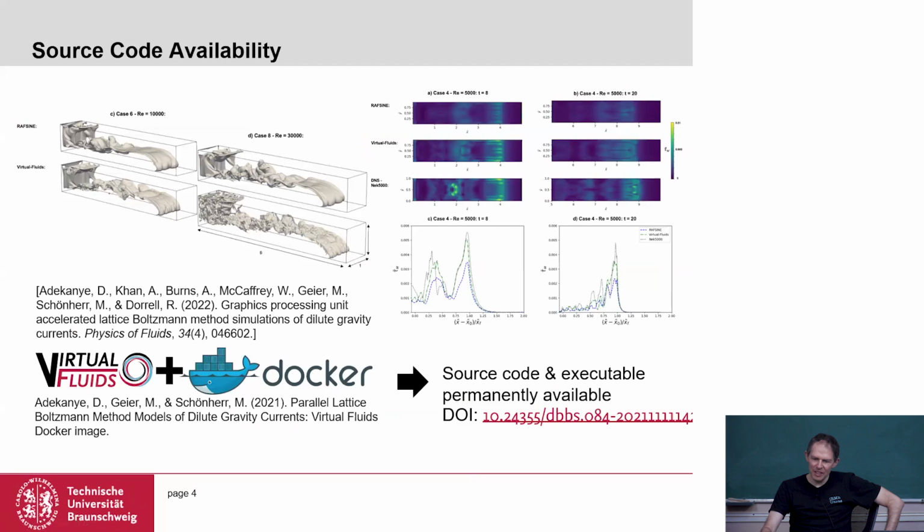Okay, so one thing that I also want to highlight is that if you want to install VirtualFluids, there are a few dependencies, not too many, but you need MPI, you need CMake, and you need Git. So these are the minimum requirements. And you need to understand and correct our mainly, maybe not completely correct, installation guide. You have it a little bit simpler if you use Docker images. We provide Docker images where everything is already installed.